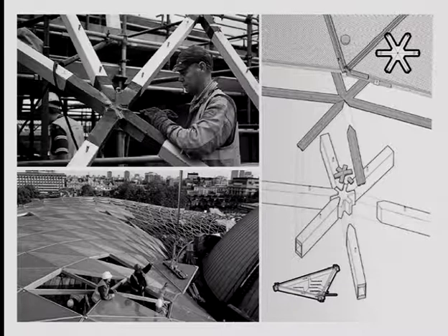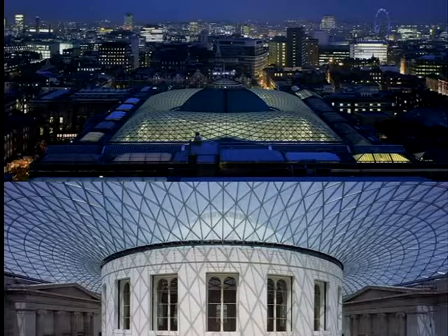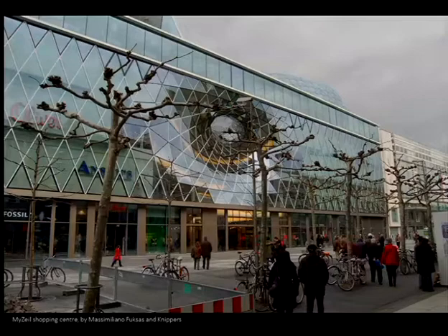And the way to build it is rather difficult because these beams are actually going in all different directions. So they made so many jigs to place them in position and define prefabricated sleeves. So you see there is a node with some sleeves, and then the beams are all planar and they are welded in place. It's a fairly complicated project, but you try to prefabricate as long as you can.